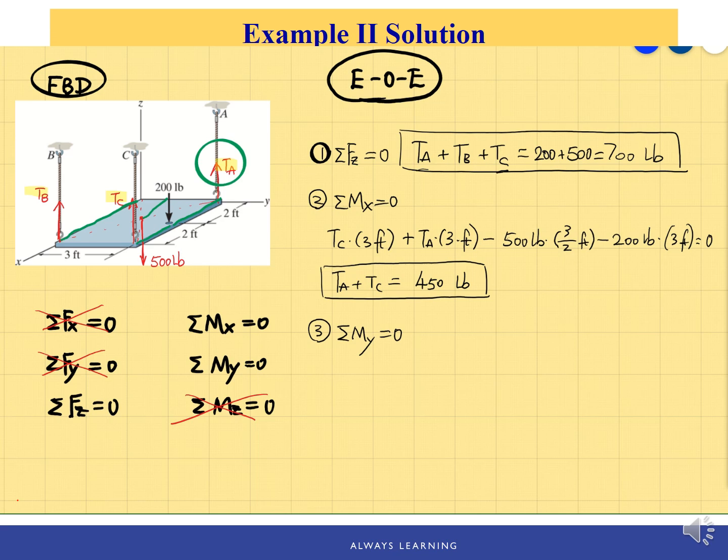So first at TB, we extend the forefingers from the origin along this green line, the moment arm line, to the force, and then curve forefingers in the direction of the force. So your palm will be facing up, and then your thumb will point into the negative y direction. So that means it's a negative rotation based on your XYZ axis.